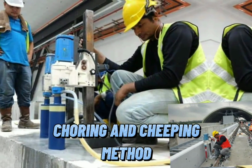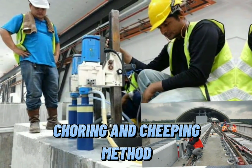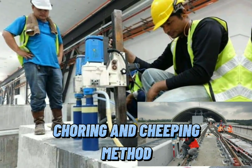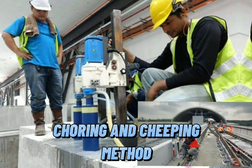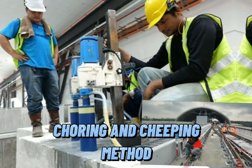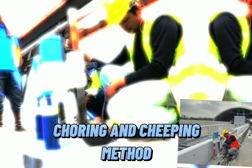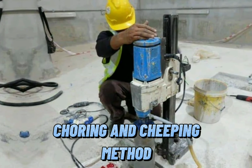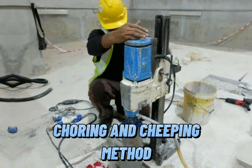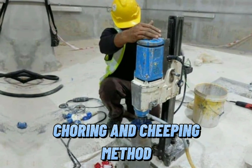Coring and chipping method. A destructive technique that uses a drilled core to create a hole in order to connect to the steel reinforcement and assess corrosion damage and the mechanical and chemical properties of the concrete. Advantages: much more information can be obtained about the health of the concrete structure using this method. Disadvantages: a destructive technique can at times be more damaging to the overall structure's integrity. Once data has been collected, the hole must be repaired.